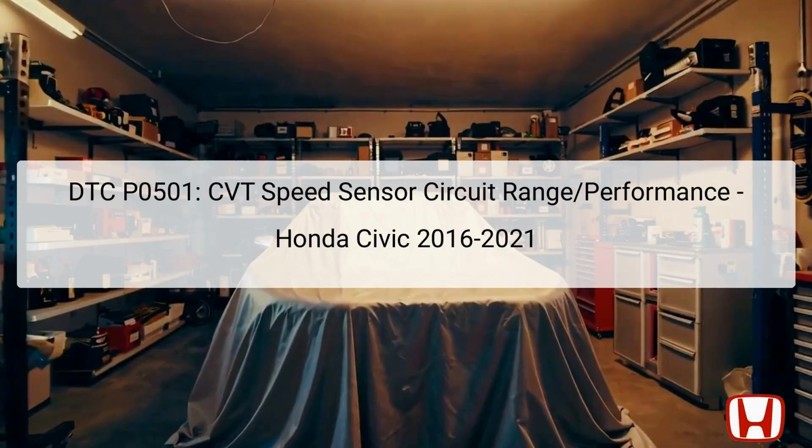DTC P0501 indicates a malfunction with the continuously variable transmission, CVT, speed sensor circuit. The CVT speed sensor is integral in determining vehicle speed by monitoring the revolutions of the secondary driven gear within the transmission housing. When operational, it sends a pulsing signal to the transmission control module, TCM, allowing the TCM to calculate vehicle speed accurately. If the TCM detects no pulses despite the secondary driven gear rotating, a malfunction is reported, leading to the storage of this Diagnostic Trouble Code, DTC.